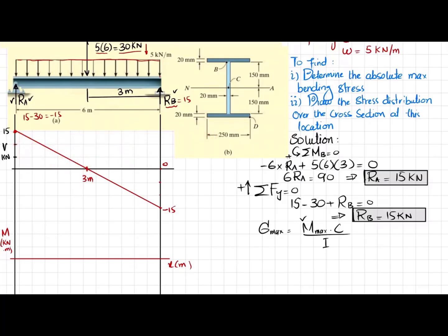So let each division be, let's say 5. So this will be 20 kilonewton, and 22 will be in between these two. So you will have a point like this. Let this be 22.5. Since this shear force line is a 1 degree line and the slope is decreasing, the bending moment will be a 2nd degree curve and it will be clockwise. So we will draw the bending moment like this one.